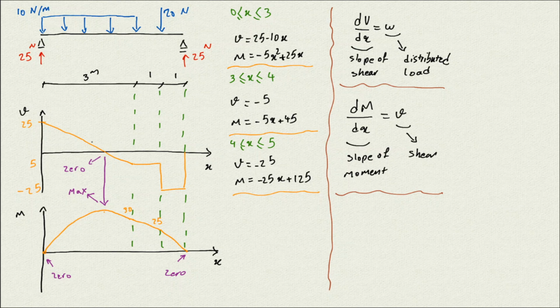So anytime that the shear becomes 0, you have to go ahead and look for the 0 slope on the moment diagram, but basically it's going to be maximum there. If it's positive, it's going to be max there. And another one to remember.